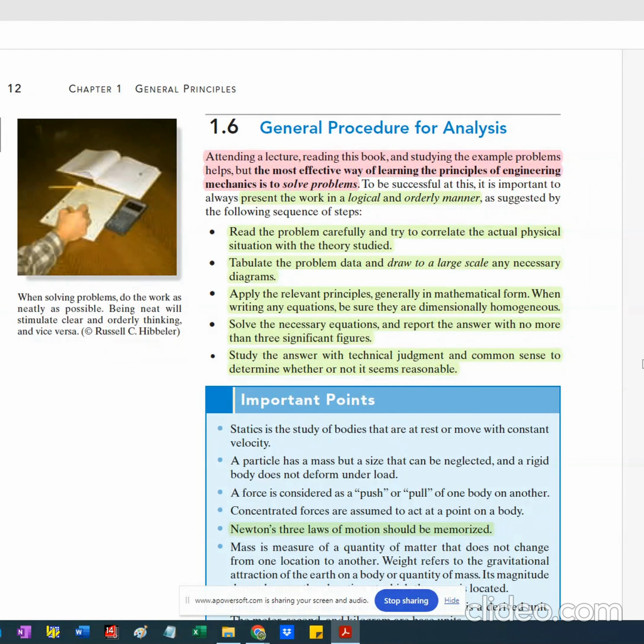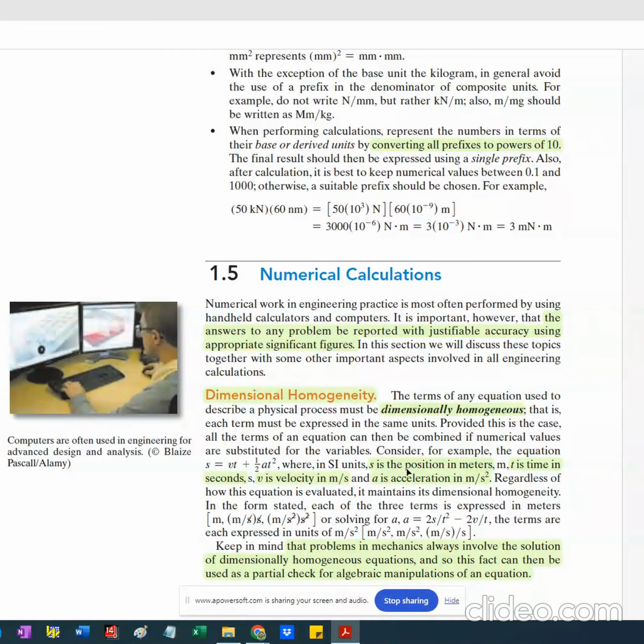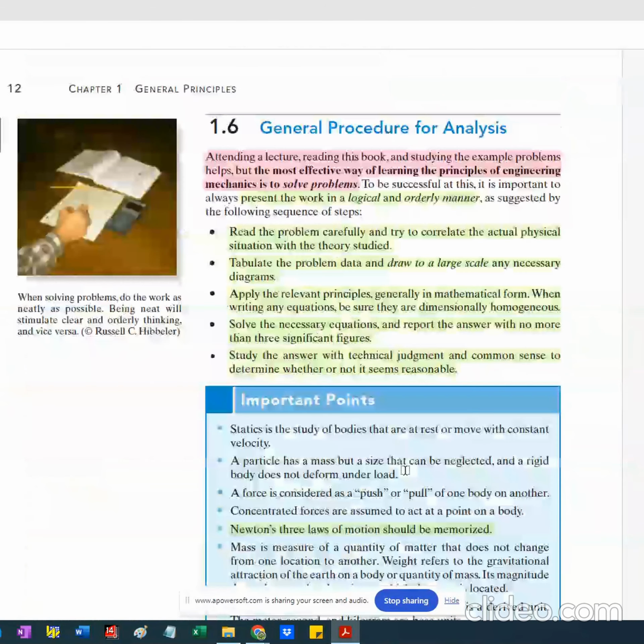Actually, that's not my style of going over problems with students. Rather, you draw, you calculate, you verify the correctness of the answer by checking: do the results look reasonable? Are my formulae homogeneous in terms of units, as we discussed earlier? So dimensional homogeneity is one immediate way of verifying results.